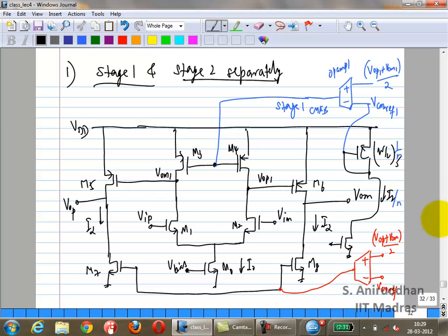Somebody said something here. Low gain. Low gain from what? Because of? Right? Adding a resistive divider would reduce your DC gain. So that was the problem with the resistive divider. What was the problem with the other one? Linearity was the problem. Swing. If you have very large swings, it's not very linear. So think about those two things and tell me which one you would use.